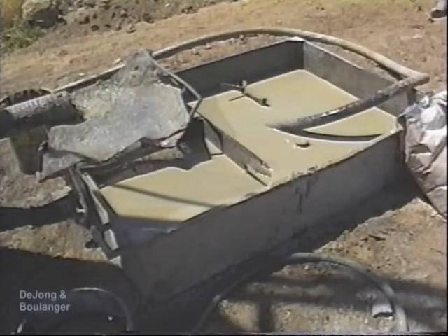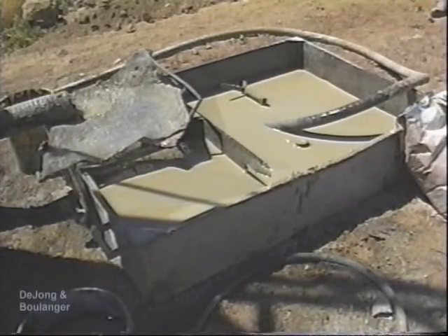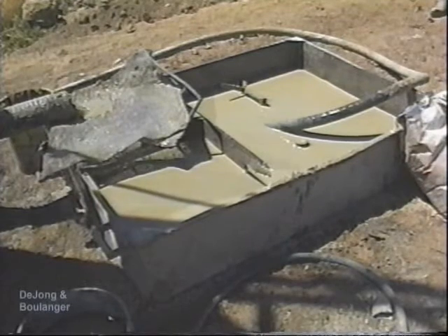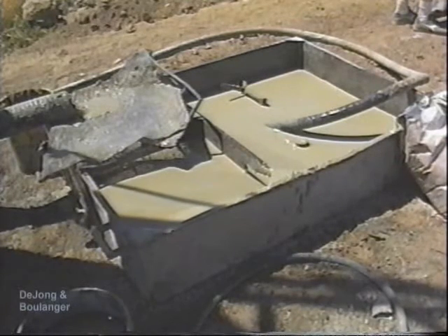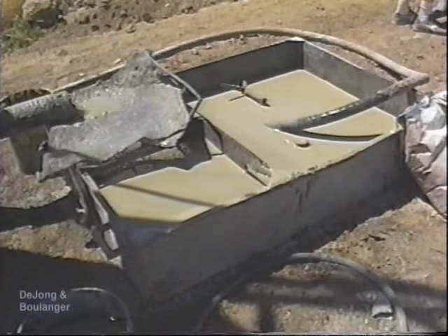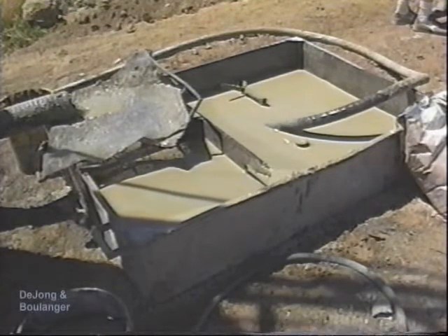The mud is a mixture of water and bentonite, which creates a slurry with a density slightly higher than that of water. This higher density helps in the removal of cuttings, preventing them from settling on the bottom of the hole. It is important for the slurry to have the correct consistency. If it is too thick, it can clog the pump, and if it is too thin, it can leave cuttings at the bottom of a hole.